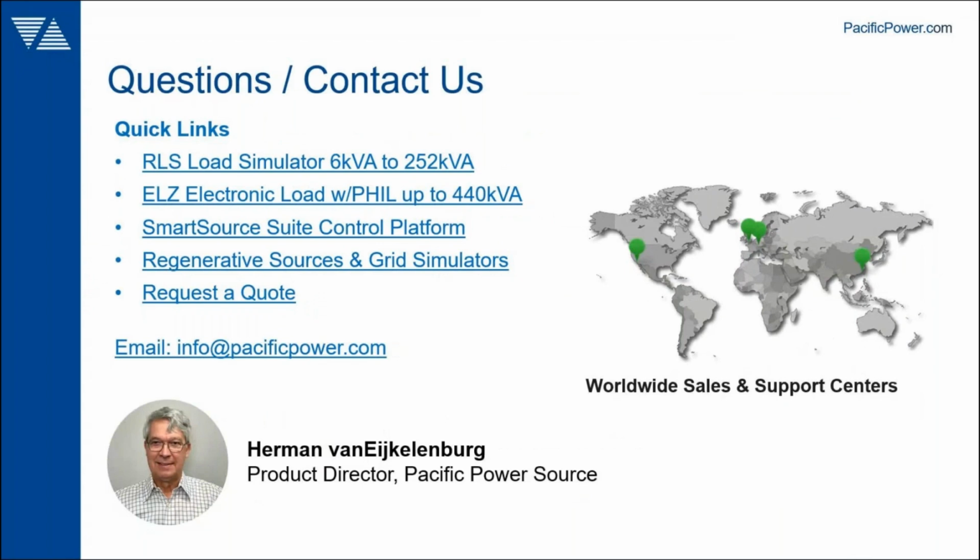Well, we were using a grid simulator in our demo setup because it gives us the ability to control the voltage and frequency that goes into the load, because it's all programmable. But if you have an electronic load and you connect it to the grid, then you obviously can, which is a source as well. It's just not programmable. It's fixed. Obviously, the utility controls it. But you can use the electronic load to load down the grid. I'm not sure what you would do that for, other than maybe testing some equipment that you have in between, or some switching gear that you have connected to it.